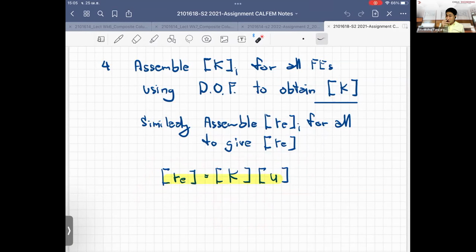And the K matrix can normally tell a lot of things. It's not only used to take the inverse of K times the force to get the displacement. Typically, the K matrix can tell the performance of your discretization and also the performance of your model, right?